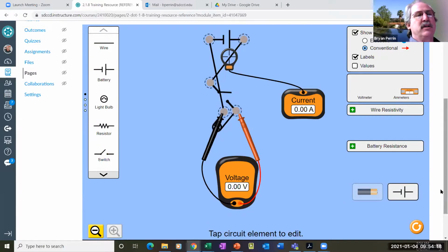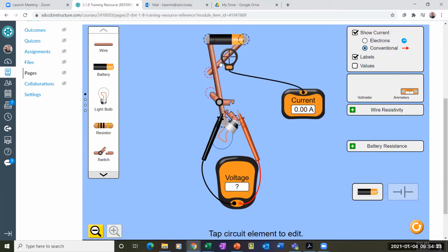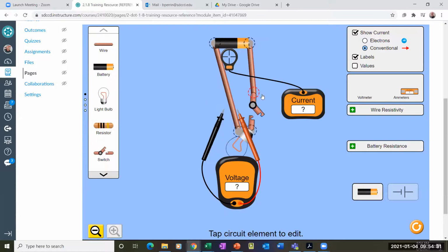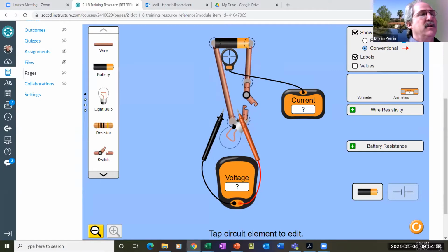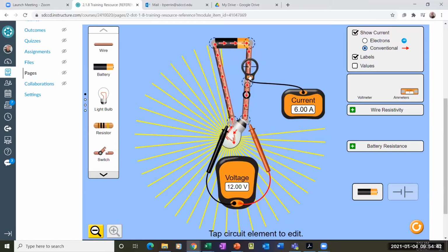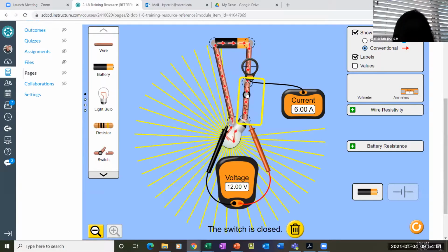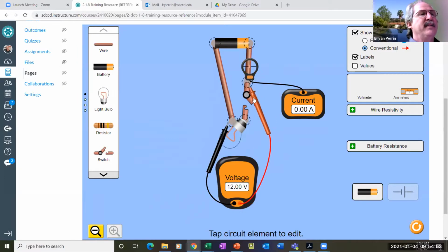You can also draw it like a schematic. So a closed circuit is also a complete circuit. Also complete circuit? Yes, you got it. So right here, I've built a nice circuit and I'm going to close it with a switch and now I'm flowing current. If I open the switch, I now have an open circuit. Over here there's no current, there's no voltage. I still have voltage up here if I test there, right? So it's all about where you test.